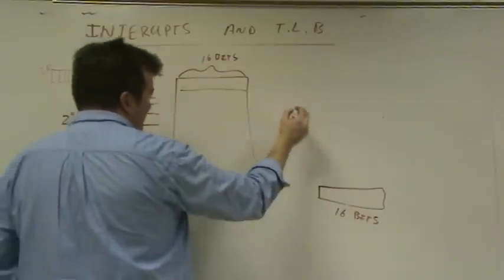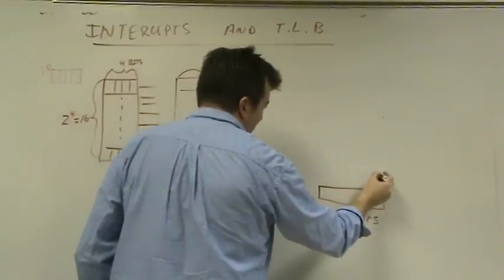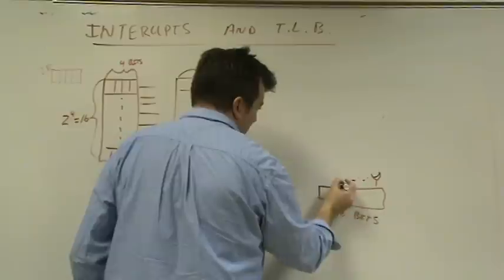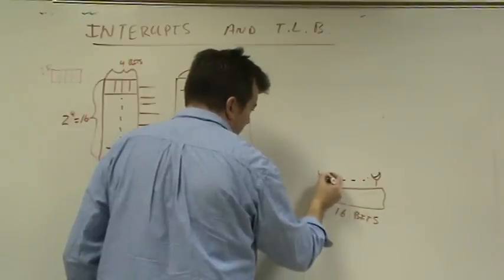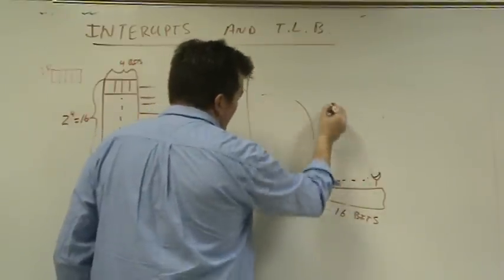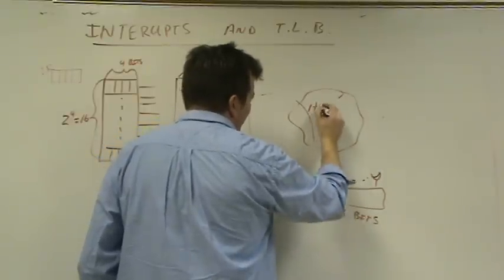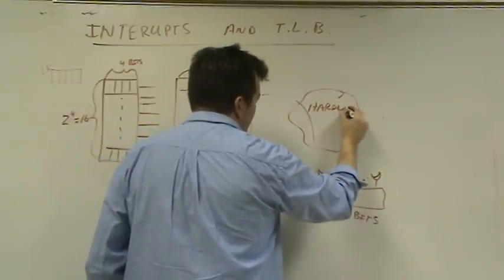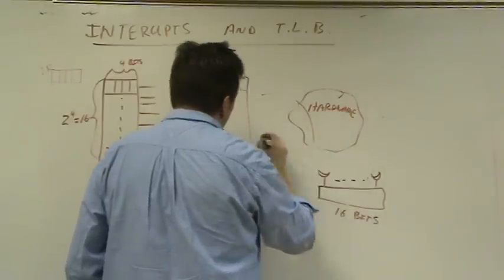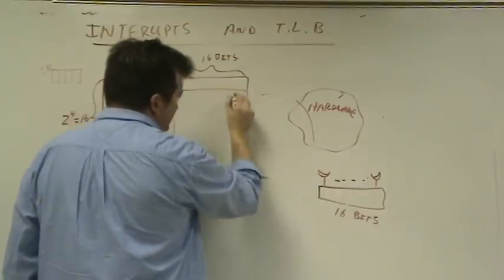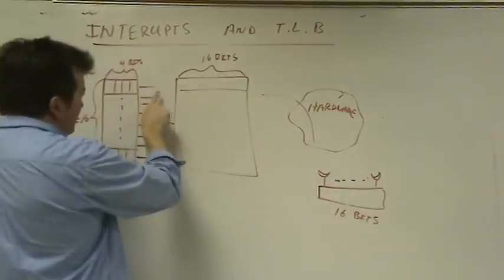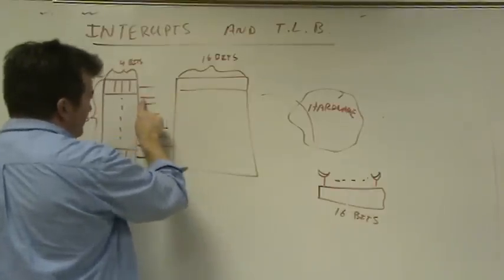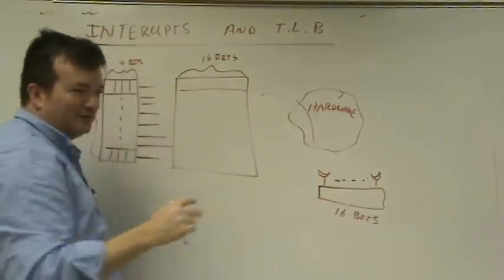So we could take all of these and run them into OR gates all over the place, and then an OR gate here. There's a whole big cloud of hardware here that will take these 16 bits and copy them here if this line is on. The next 16 bits, if this line is on, will get copied here, and so on.